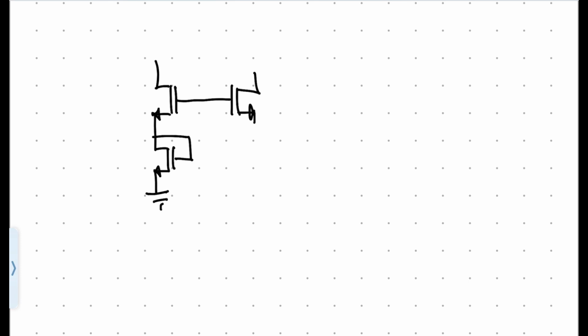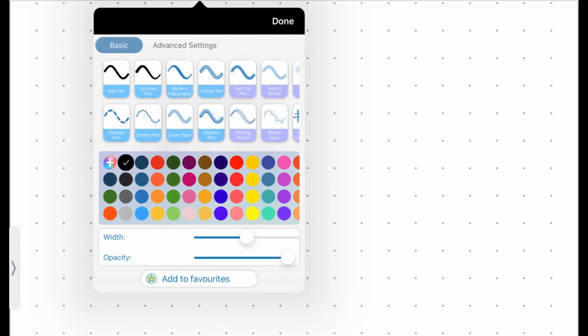Welcome back. Today I thought I would show a quick design example of a current reference that is generated using a threshold voltage. If we take a current mirror and put a diode NFET underneath it like this, and add a resistor underneath the other FET, we can generate that current.